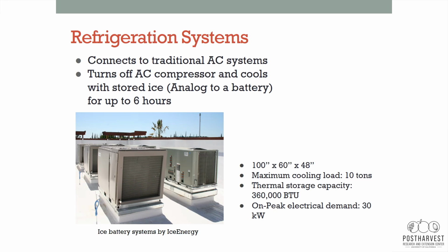In this case, for example, this schematic is analogous to an ice battery. If we turn off the compressors and cool with stored ice, we can cool for up to 6 hours without the need of additional energy. Even though energy is required to produce the ice, the dissipation or loss of heat in these chambers or batteries is much more efficient.